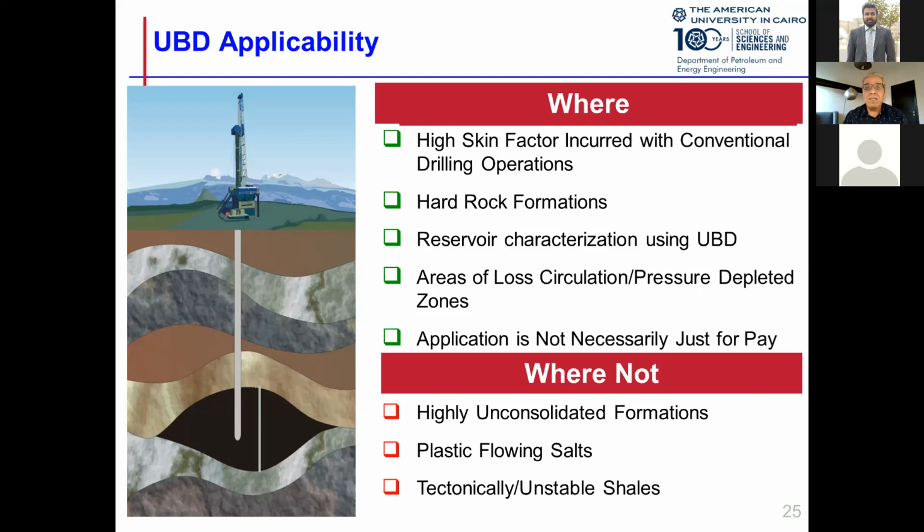And of course, there is other technology associated with underbalanced drilling. So we need to see our reservoir before we approach the top of the reservoir. Different techniques exist. For example, when we get closer to the reservoir, we can use gas chromatography, GC units.